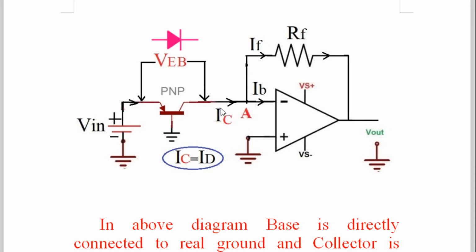Vin minus VA. And then here when you come to the RF, voltage across RF, when you want to measure by voltmeter, then you connect voltmeter over here such that one terminal to the left hand side and one terminal to the right hand side. On right hand side there is a V out, on left hand side there is a VA. Therefore here the voltage across feedback resistor will be, right hand side voltage will get subtracted from left hand side. Therefore VRF is equal to VA minus V out. That is the way with which we can write the voltage across feedback resistor.